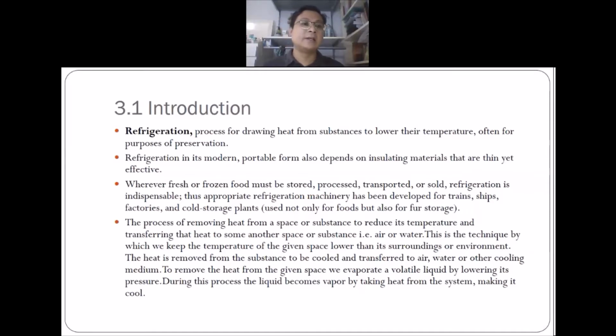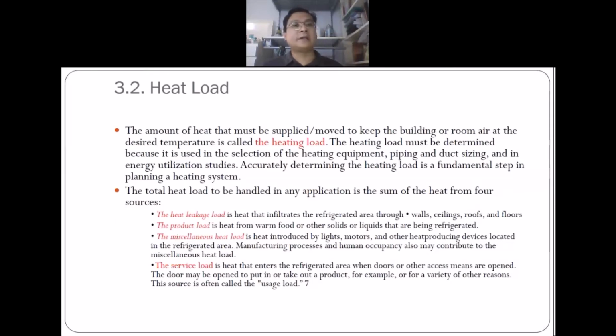Okay, now we go to the next subtopic about heat load. So what is the heat load itself? The amount of heat that must be supplied or moved to keep the building or room air at the desired temperature is called the heating load. The heating load must be determined because it is used in the selection of heating equipment, piping, and duct sizing in energy utilization studies. Currently, determining the heating load is a fundamental step in planning a heating system.